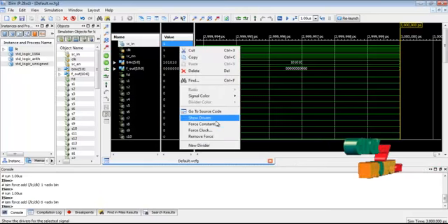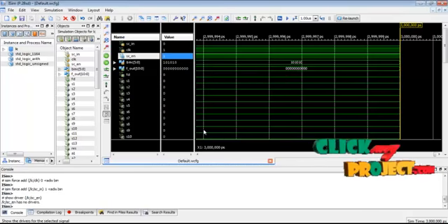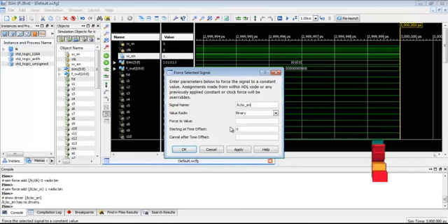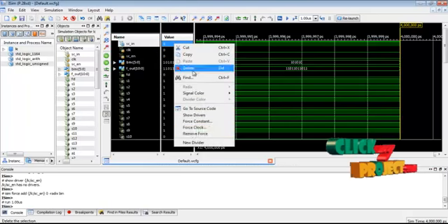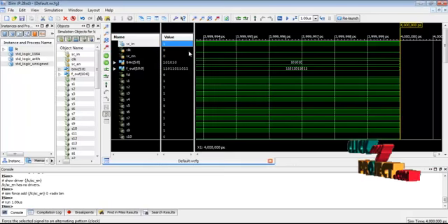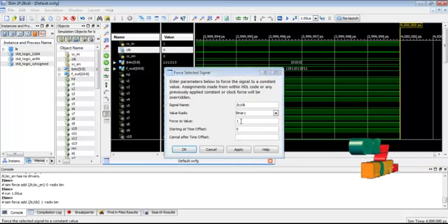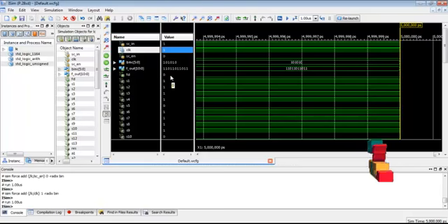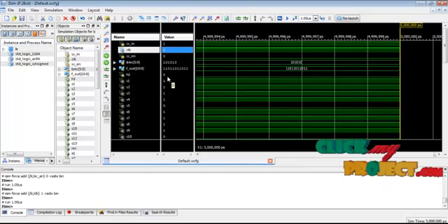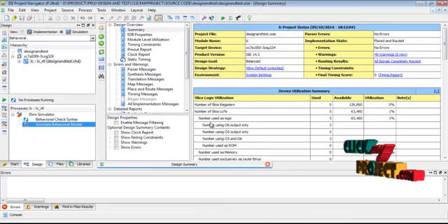Then we activate the scan input signal and deactivate the scan enable signal. Apply the clock fully. Then we get the output test pattern results, and finally the fault detecting signal is 0 in the simulation result. We certify the testing architecture simulation result.